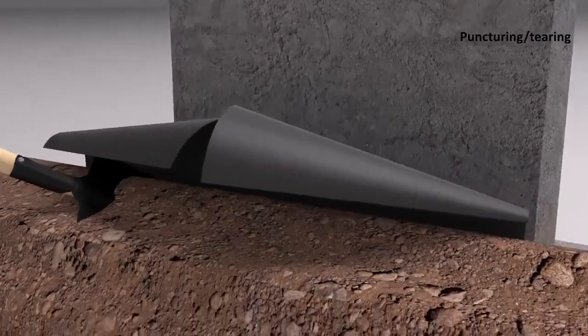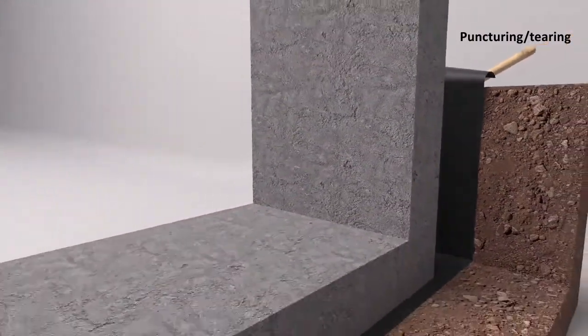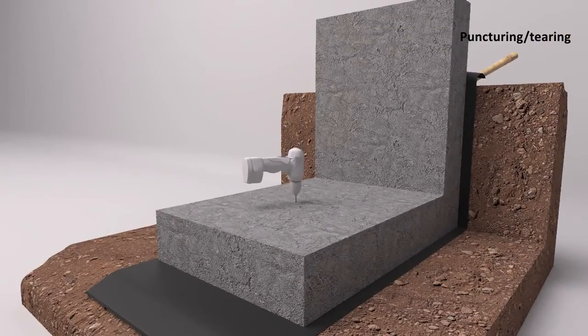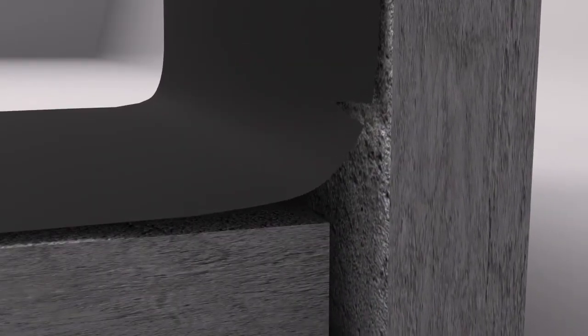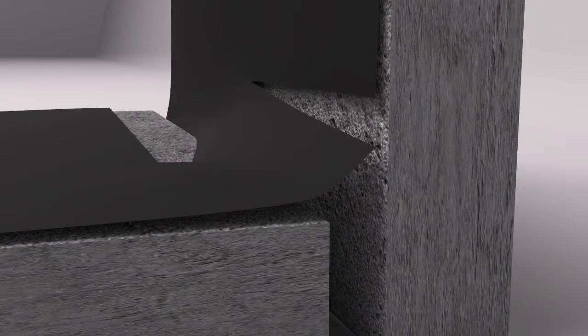Waterproofing membranes are exposed to a high risk of damage. Often, this damage occurs in the subsequent stages of the construction schedule. Puncturing often occurs, for example through concrete drilling, backfilling and pipe installation works. Tearing of the membrane usually is the result of building settlement, building movement or expansion joints. Both puncturing and tearing represent a breach of the waterproofing layer and thus a failure.